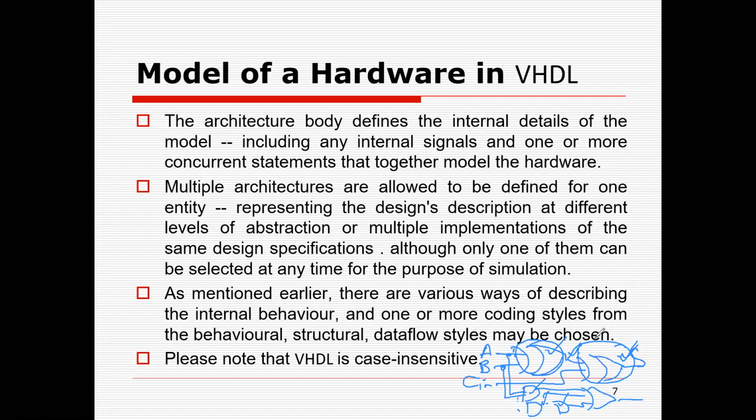I may design an adder using XOR and OR gates. I can design the adder with only NAND gates. So these are two different circuits. The input-output behavior is the same, the interface is the same, but the way I define the internal structure could be different. Okay, but when I'm doing a simulation, I'll pick up the entity and one of the possible architectures. I can write many architectures, but simulate one at a time.